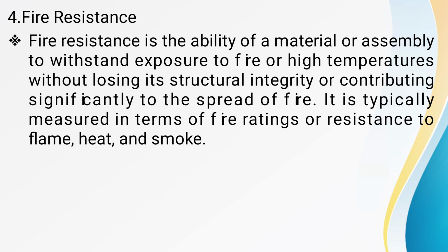So when we talk of fire rating, we have materials that can be rated for the ability to resist fire and to prevent its spread. The ratings are usually commonly done maybe in 1 hour, 2 hour rating, 3 hours, etc. Then you also have the other aspect of flammability. Here we have materials that can be classified as non-combustible, fire resistant, or combustible based on their reaction to fire.